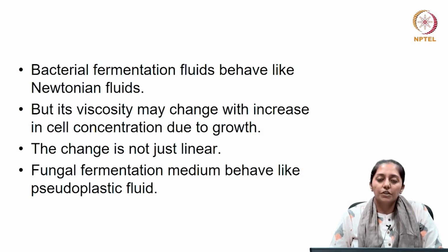There, with time you may observe that the behavior deviates from a Newtonian fluid to a non-Newtonian fluid. So the change which you will observe may not be a linear change. Another example is fungal fermentation medium, which behaves like pseudoplastic fluids, which are called shear thinning fluids.